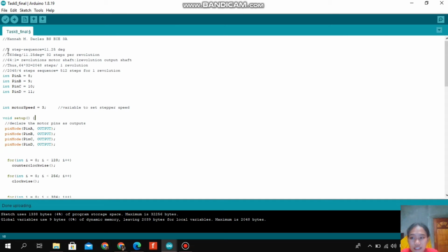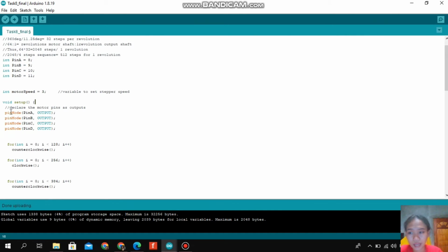As you can see here in this part, I declared pin 8 to be our pin A, pin 9 to be our pin B, pin 10 to be our pin C, and pin 11 to be our pin D. And I just put the delay or motor speed to 3. Now here in our void setup, I declared pin A to pin D as our outputs.